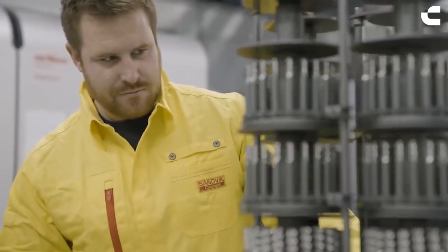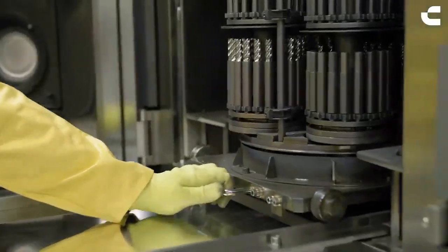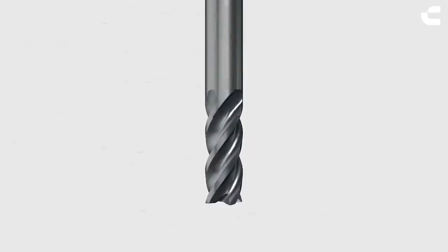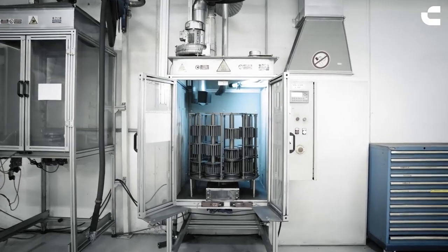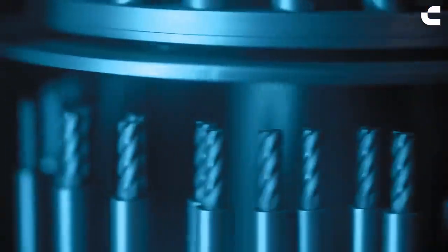We place it in a vacuum chamber where a mixture of gas is injected. As the temperature increases, a thin layer of metal carbon nitride coating is applied to the tool. It enhances resistance to both heat and wear. This process takes between 4 to 5 hours, and the temperature of the chamber reaches more than 500 degrees Celsius. High-pressure air is then used to remove dust and debris to ensure optimal machining results.